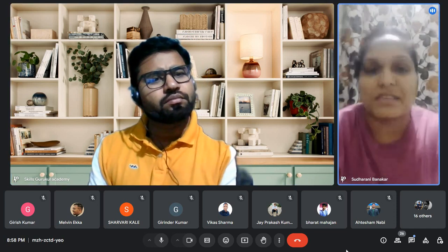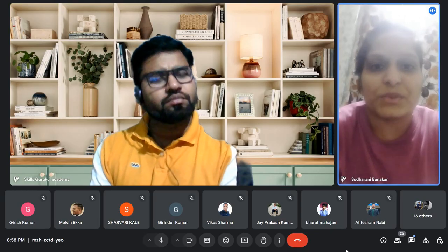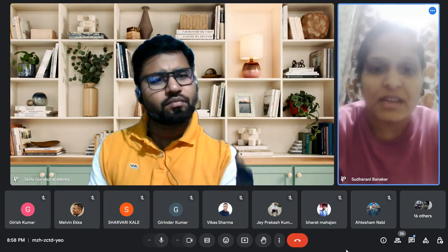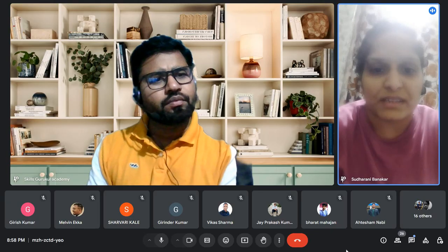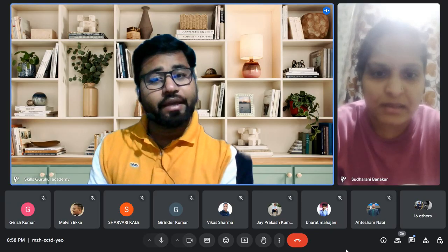Okay. What do you understand by crank bar? Crank bar is provided in the inclined portion at the end of the beam, sir. It is provided at 45 degrees. Okay. And what do you understand by anchor bars?